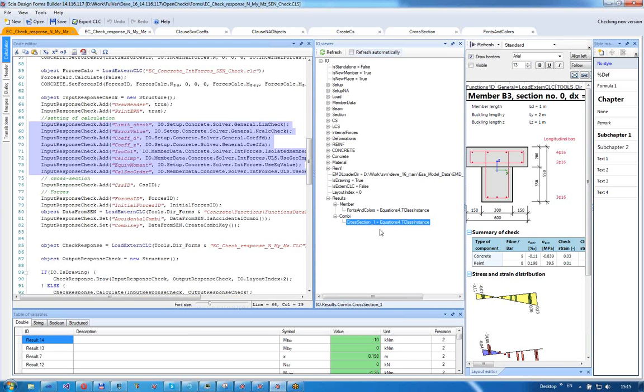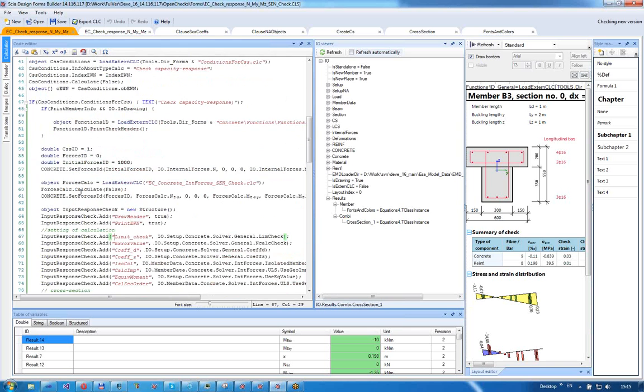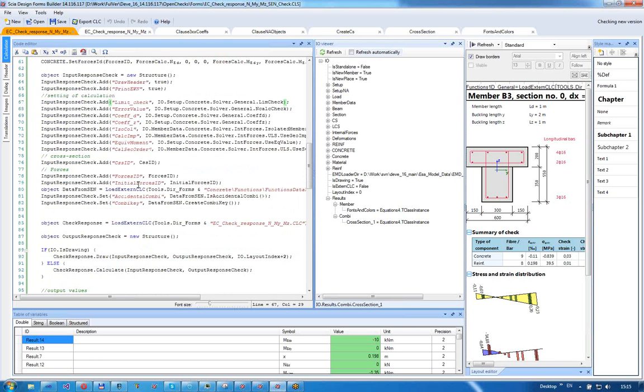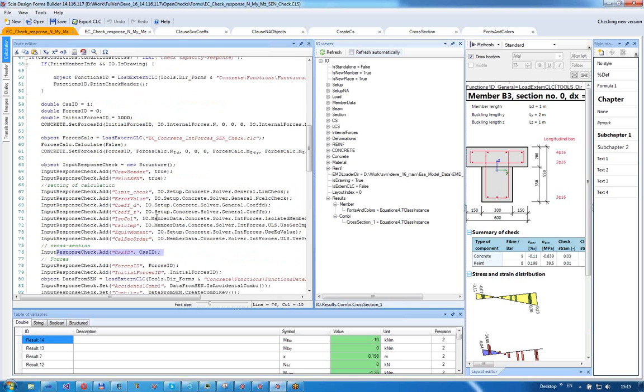For example, these cross-sections are here saved with some unique ID. In this case, it's the ID that is passed to the calculation templates. As you can see here, it's an SSID, and SSID should be unique for every type of cross-section. For example, the ULS cross-section has ID 1, the SLS cross-section has ID 2, and the different cross-sections, for example, with a different type of diagrams, or maybe even without reinforcement and other stuff, should have a unique ID, and this time they are created only once.